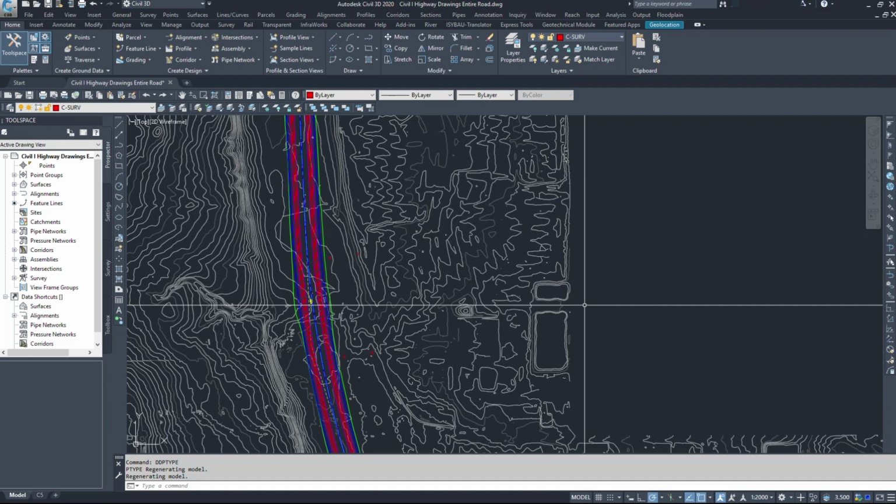Now, in the city of Calgary, we're pretty close to the city here. They use a specific number for their water storage. So when it rains, they'll say 70 liters per second, 90 liters per second, etc. And that's the number that they will use for their water. This is times by the area of the land. However, because this is a provincial highway, we're going to follow the Government of Canada rainfall design standards.